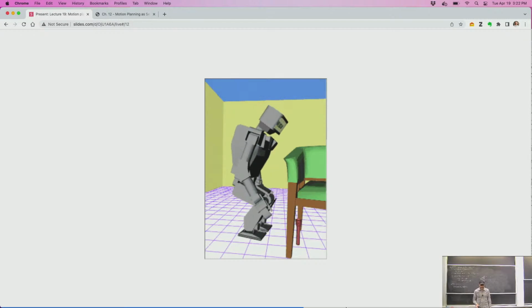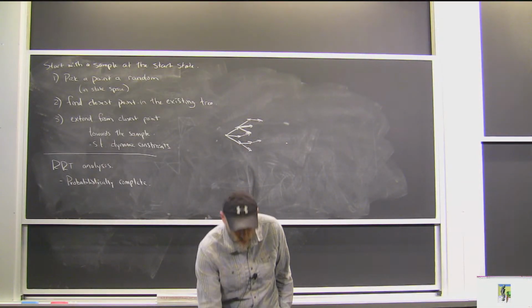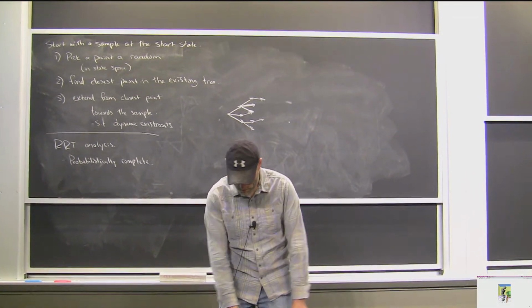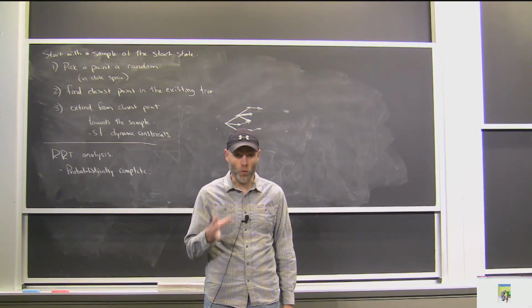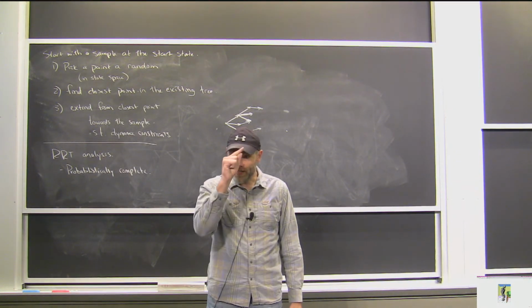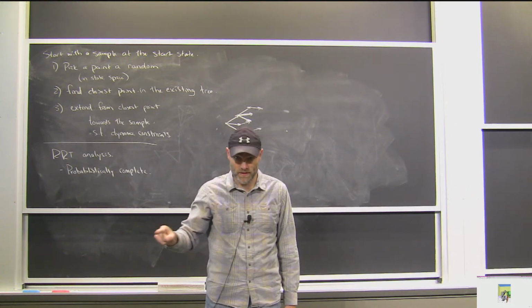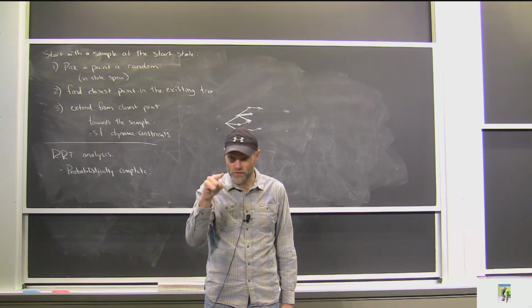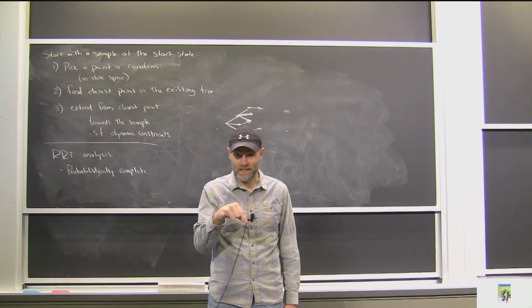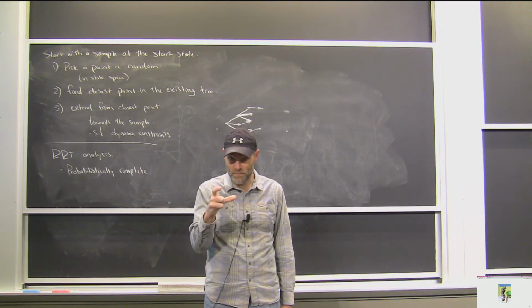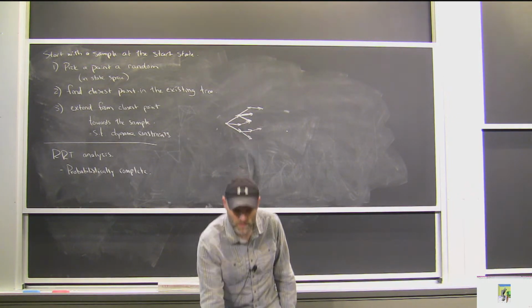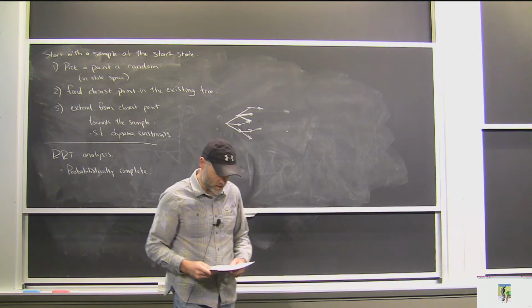So he actually just plans the trajectory subject to a constraint that the center of mass always stays over the support polygon. Okay, and he only plans in the positions of the robot in order to reach down. And then in order to execute the plan, he will speed up the trajectory. He'll execute that at whatever the largest velocity he can manage that keeps the zero moment point inside the support polygon. Okay, so he uses ZMP as a constraint, a rate limiter, roughly, to execute a dynamic plan as he's moving his body around.